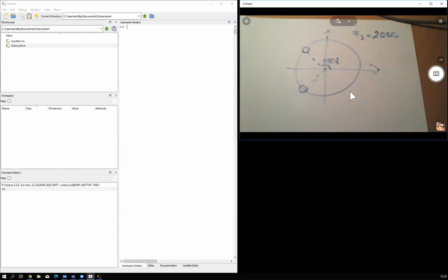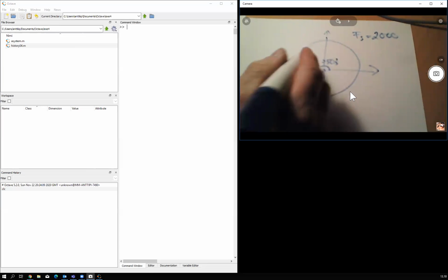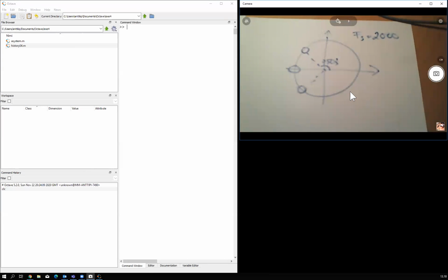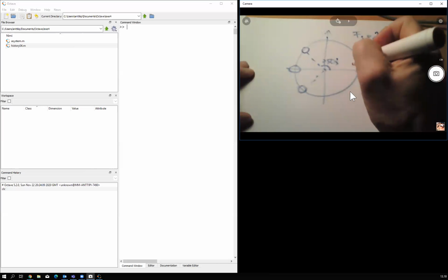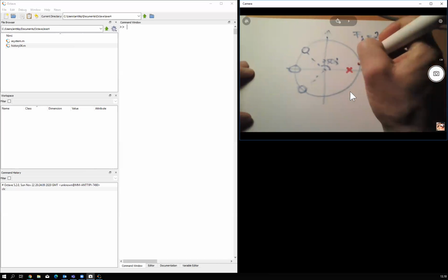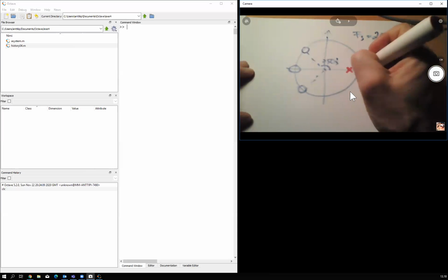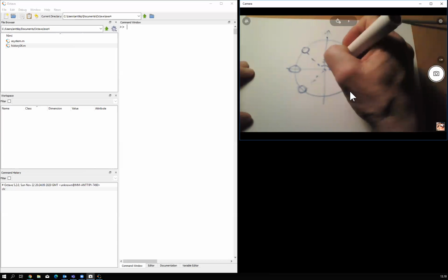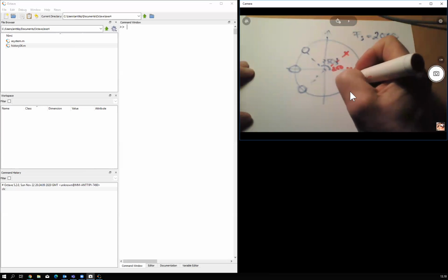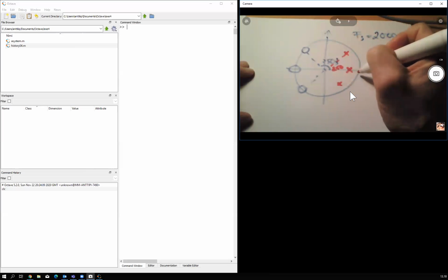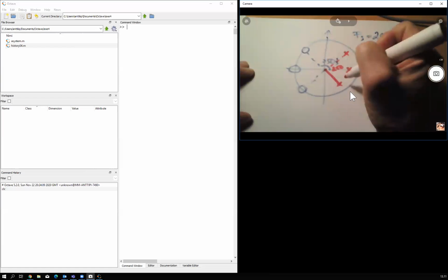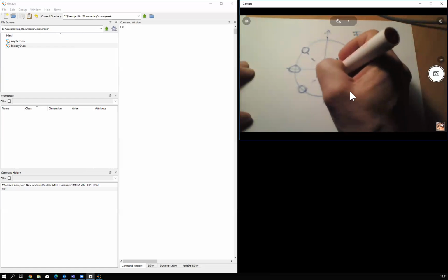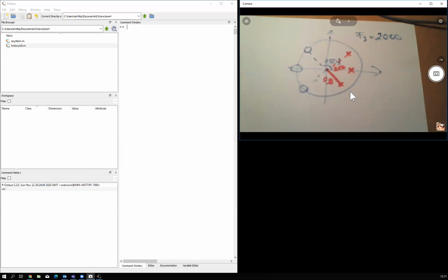And then we have the system gain. We could also add a zero at 1, so we have three zeros, a third degree system at least from the zeros, and then just put some poles, one pole here at distance 0.2, and then maybe at 250 hertz a pole pair, and the radius from the origin would be 0.8. This is our system, zeros and poles.